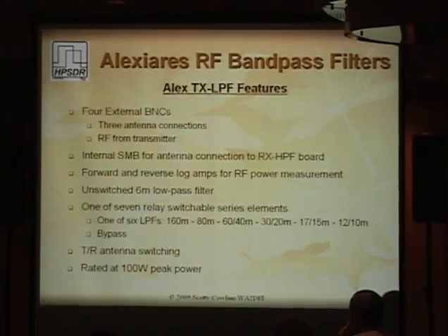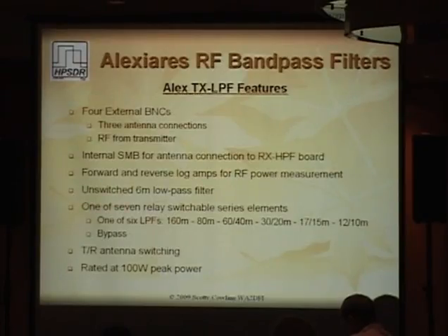It's got 3 antenna connections, so it's kind of a station console integrated in. The only thing it doesn't have is an ATU. It does have forward and reverse log amps for RF power measurement, and there's a port on, I believe it's on Penelope, where you can actually read the forward and reverse power from the Alex board in software.